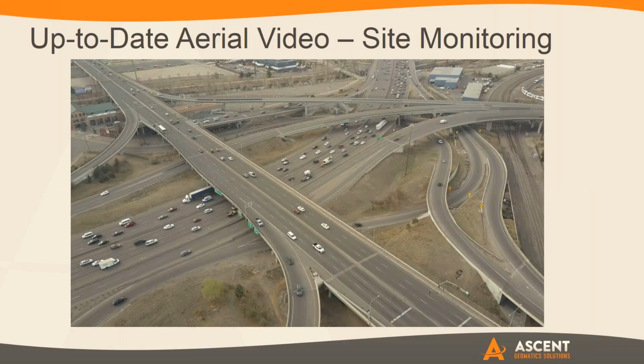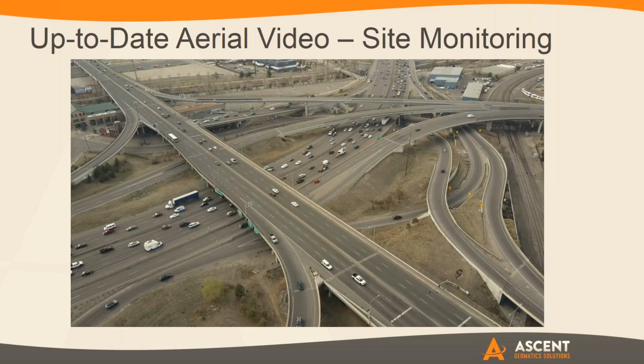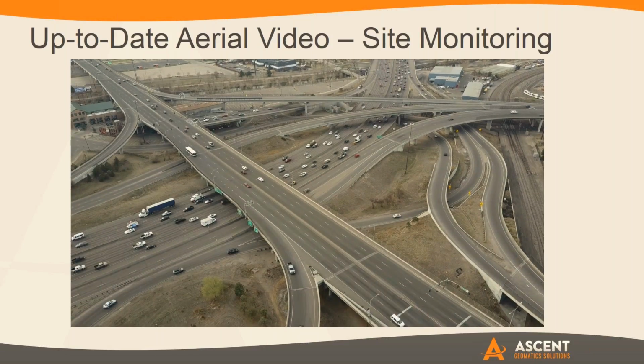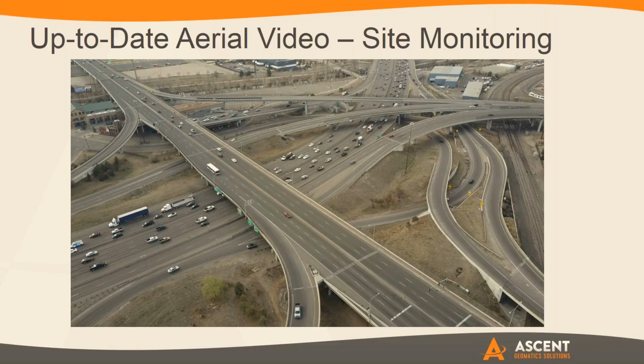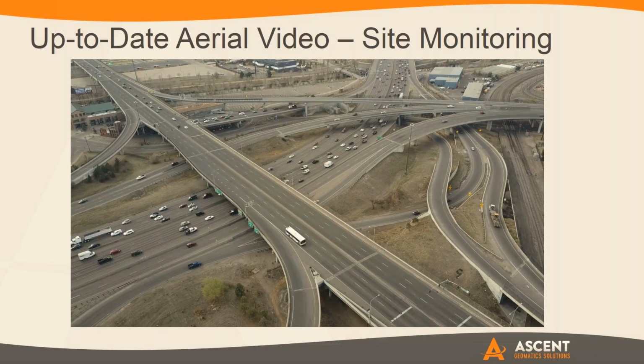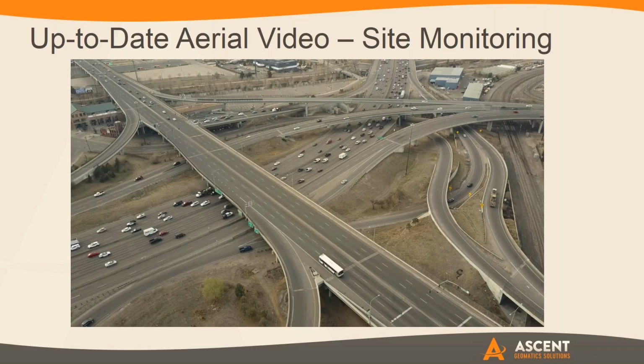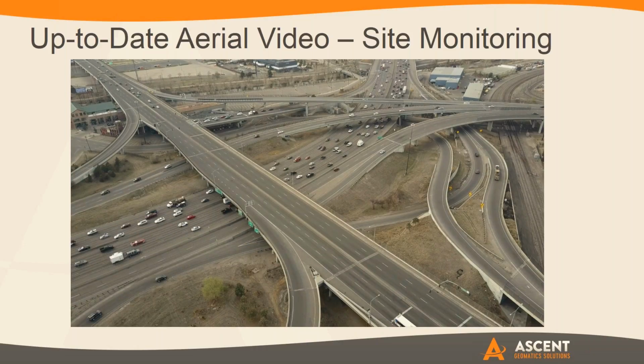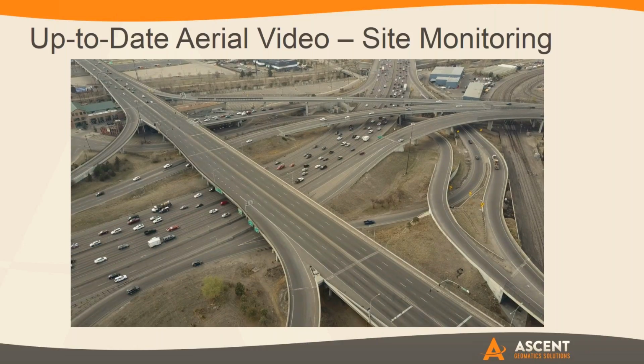I think this next slide even ties further into that. We mentioned video monitoring before. Get out at peak rush hour, get out at different times during the day, and see what the volumes and traffic patterns are doing. Where are those choke points? When you drop from a 4-lane to a 3-lane, how does that affect traffic, and how far out? By having some simple video of a given space, like this example, you can learn a lot from it, and you can also develop it into your true traffic counts for your actual front-end development.